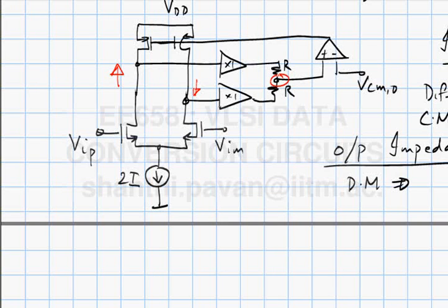That node remains the same. Okay? If that node remains the same, what can you say about this node? That node doesn't change either, because that's simply an amplified version of this node voltage. So in other words, if I apply a fully differential voltage excitation at the output, this node doesn't change. So incrementally it is equivalent to grounding it. Okay? So in the small signal picture for differential operation, you can ground the gate.